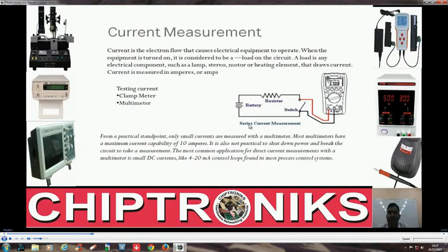Measuring current is required when voltages at each of the specified locations in an electronic PCB circuit are correct, but your device is not operating in the right condition. In that case we have to observe whether the electronic component is taking the right current.